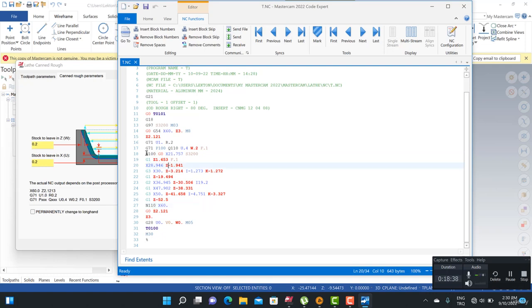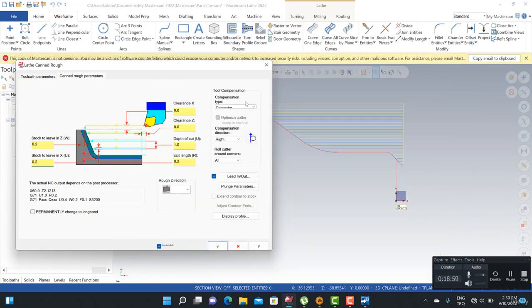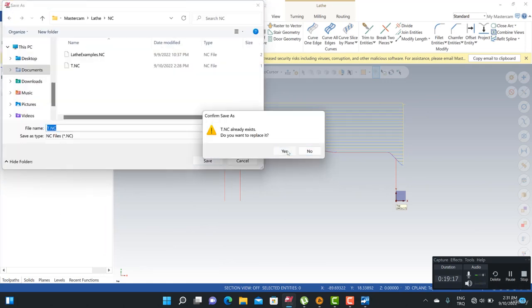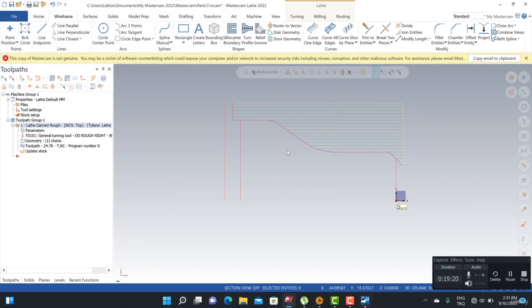So that's all my figure. Actually, we can see that this is the vector approach while we are creating circular interpolation G2 and G3, I mean that. But we can also see some decimal numbers, but that's all okay. You know that's all because of the tool compensation. Okay, if I use the contour options, I can click here and click the OK button. If I get my G code again, we cannot see that kind of decimal number at that point.